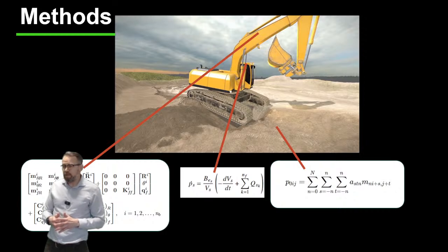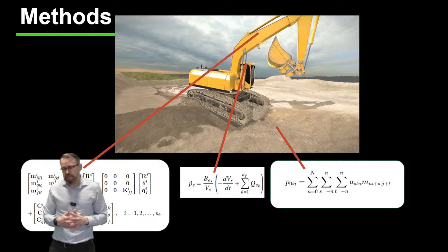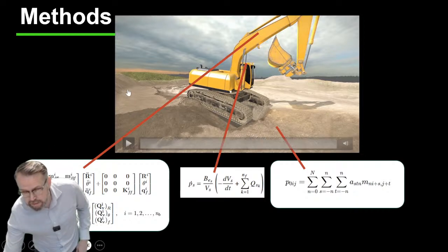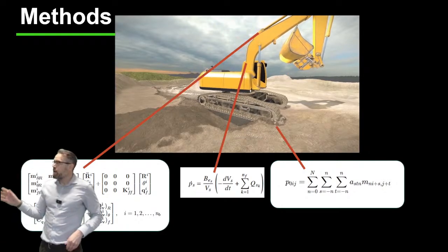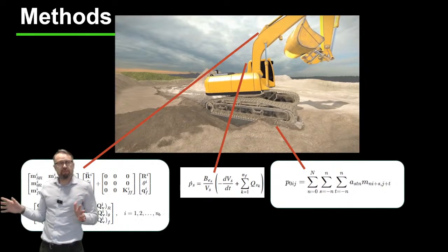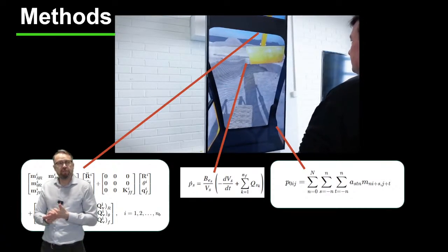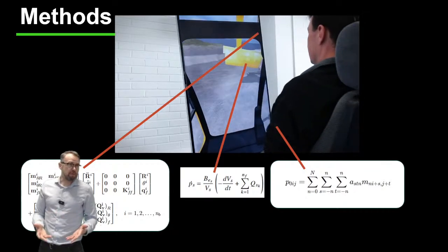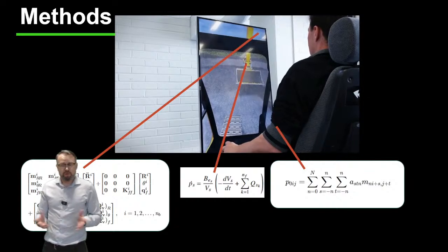Hydraulics, as can be seen here, can be modeled by a technique that we developed at LUT University a while ago, and the interaction with the environment is going to be based on particle dynamics and height-field technology. Now, all these can be put together and solved in real time, as can be seen here in this animation. This simulation comes with a major drawback: all the bodies are assumed to be rigid, making it not possible to predict accurate loadings and stress histories that are imposed on the welded joints.